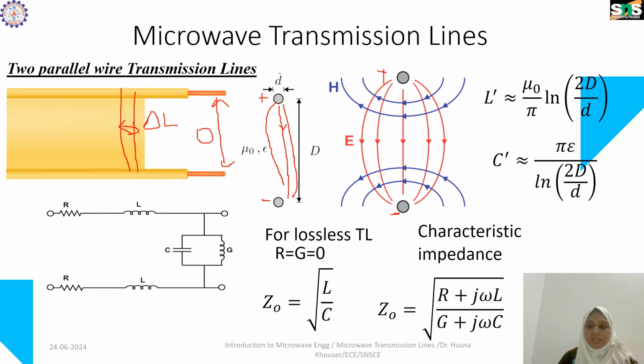This is a basic transmission line diagram, and this basic model is the same distributed model used for coaxial cable as well. Here the cross section of the transmission line is modeled using the fundamentals of resistance and inductance, together with capacitance and conductance, which we call a tank circuit.